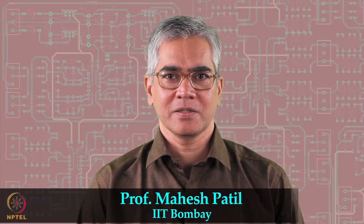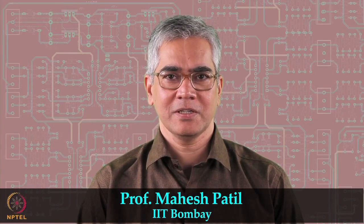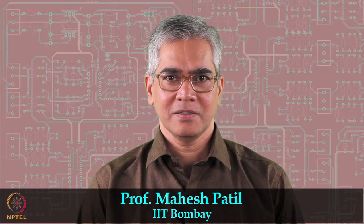To conclude, we have seen that the instrumentation amplifier offers a high input resistance and a high CMRR, and that makes it well suited for sensor applications. We have looked at two additional op-amp circuits, the current to voltage converter and the integrator. In the next lecture, we will look at some non-idealities associated with an op-amp and how they can affect the circuits we have considered earlier. So see you next time.